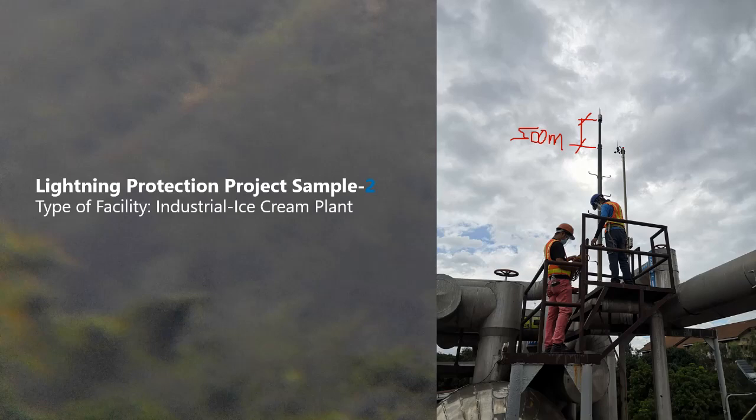So limit the distance, because we want our lightning protection to be at the topmost or the highest elevation, so that it would not be affected by what is below the air terminal. We want to protect our system, so we also want to isolate the strike at this portion, so it will not include anything below this level. That's why I recommend not to install like this one.